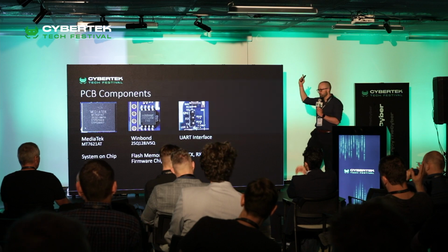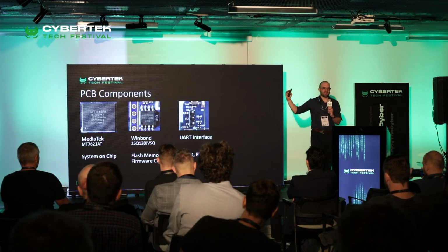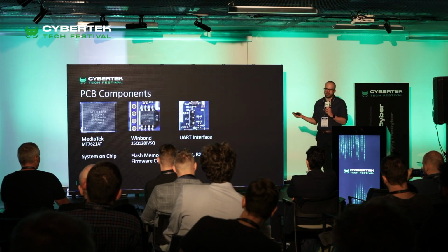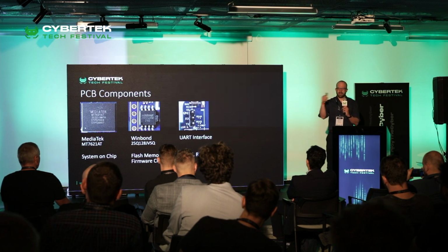This already screams UART in your face, right? You have GND, RX, TX, and honestly, this is easy mode in hardware hacking. In other devices, you have pins or pads scattered around the PCB, so this much more turns into a scavenger hunt. But great, now we identified our target.